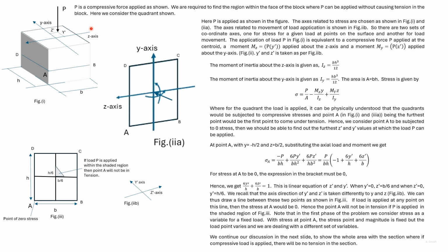We are required to find out an area within which P can be applied so that the stress on a section such as A, B, C, D will be compressive, and the area has to be found within this quadrant.